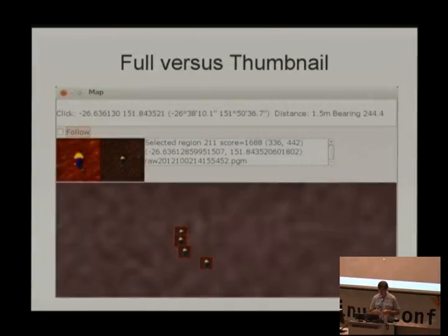But we managed it. So one of the tricks is, first of all, you don't need to send the full image. As long as the image recognition algorithm in the plane is working well and it identifies just a few pixels around interesting blobs like Joe. This is when we found Joe in the competition. There's Joe. And you only need to send just those little tiny thumbnails surrounding Joe. And then you can concatenate them together and compress the hell out of them using JPEG and squirt those across a link, and each one comes down to being less than 2 kilobytes, sort of 1.5 kilobytes or so, which means you can send roughly one of those per second or so across this 2 kilobyte per second link.